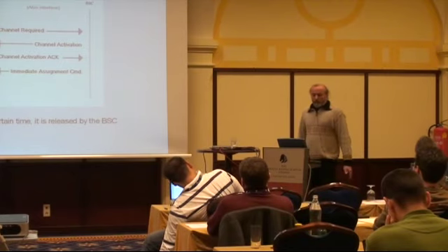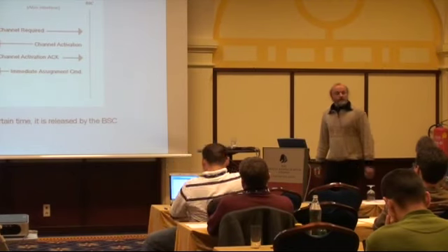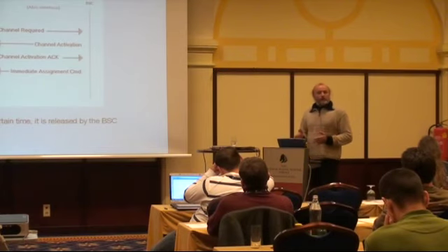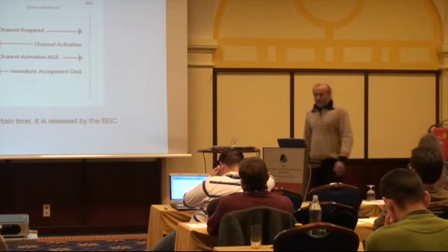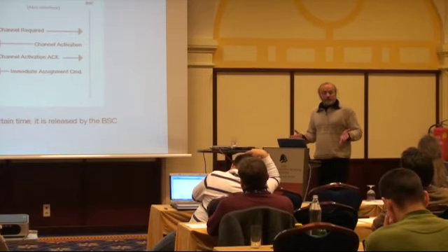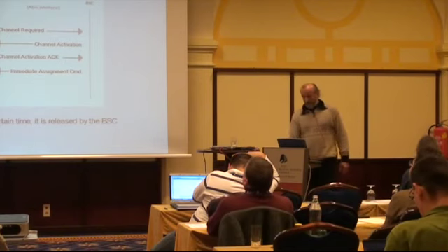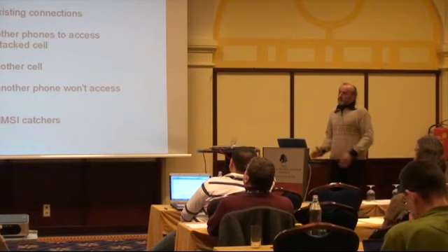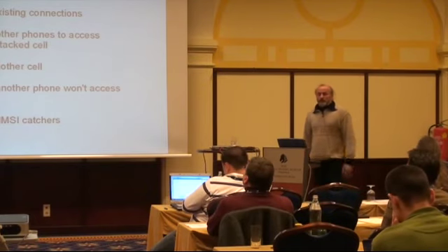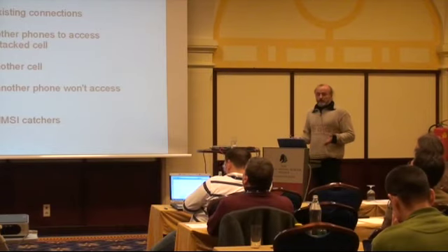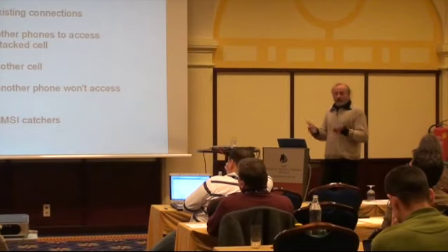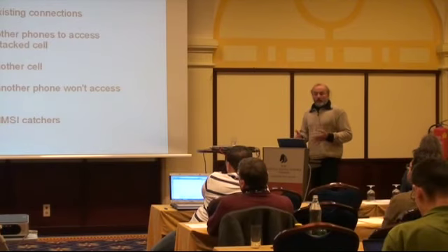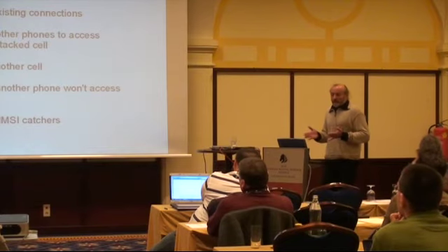If you continuously send those channel requests, you can send around 100 to 200 channel request messages per second, depending on the configuration. You can imagine if you only have around, let's say, 40 channels, they are exhausted really soon. The effects of continuously sending RAC bursts, and by continuously I mean you send the RAC bursts in every possible slot: two different configurations are possible. One is you can send about 200 bursts per second. The other configuration is you can send 100 bursts. But this is really sending a burst in every possible position.